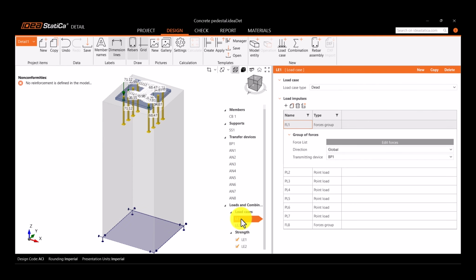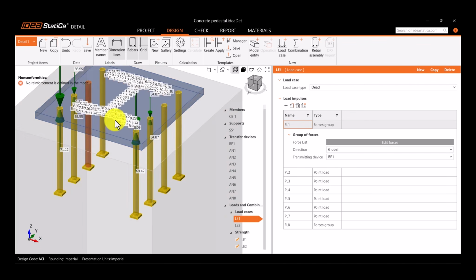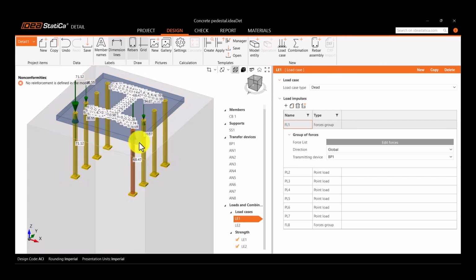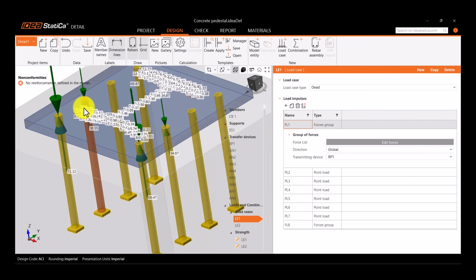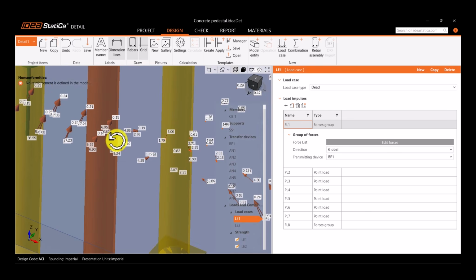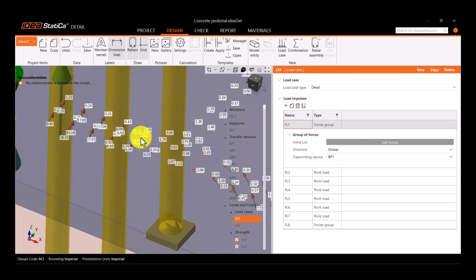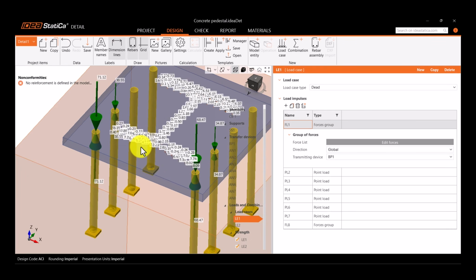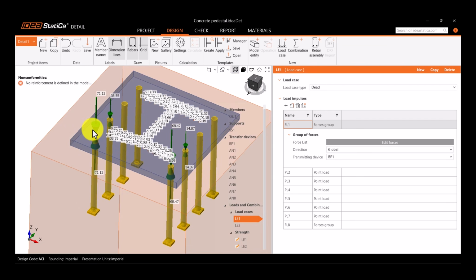And then also you can start looking at the load cases. So the forces in this base plate and the anchors were imported from the analysis in connection. So you can see that we're importing the forces coming from the welds into the base plate. So in that case, we distribute the force into the base plate in a more realistic way, right? Then we are also importing these forces here into the anchors.